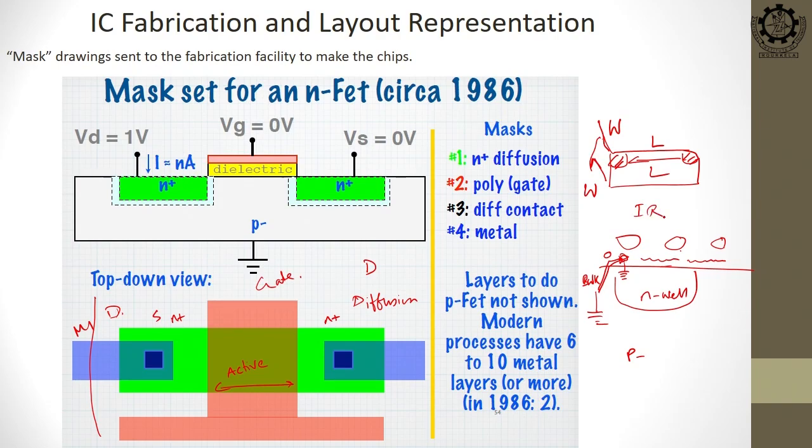Some current will flow through the substrate, all the parasitic diodes, all the leakage current, will flow through what? Substrate. All of these diodes, some reverse bias current will flow through them and they will go through this resistance and then to this ground.